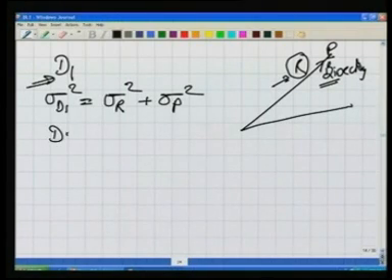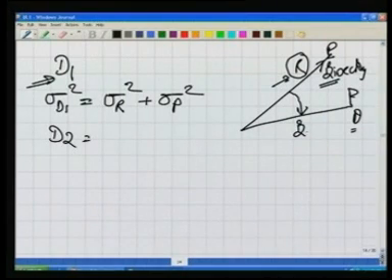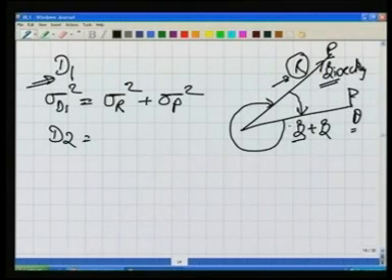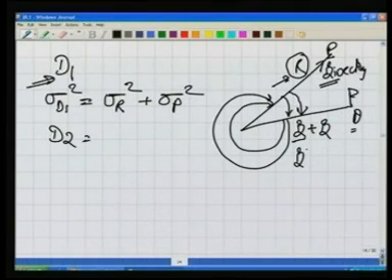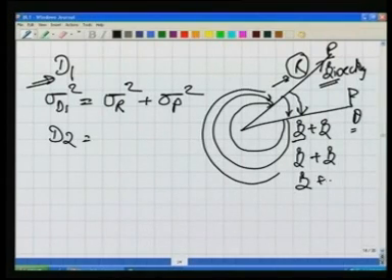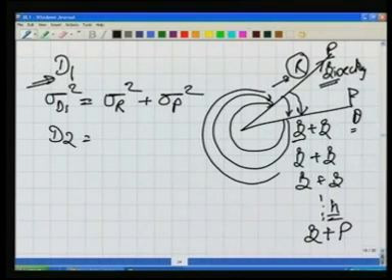While in the case of D2, what are we doing? For D2, we have P and Q. For this Q, we come over here and bisect it, we again close the horizon and again bisect it. So one more bisection. Now again we come over here, one more bisection, we close the horizon, one more bisection, again we come over here, so bisection plus bisection, and finally after doing this n number of times, we do our final bisection and the reading.